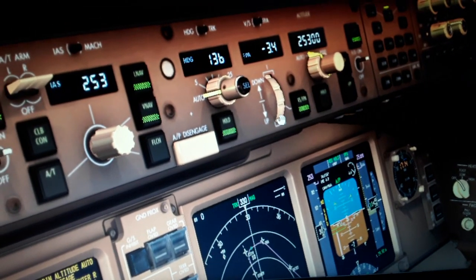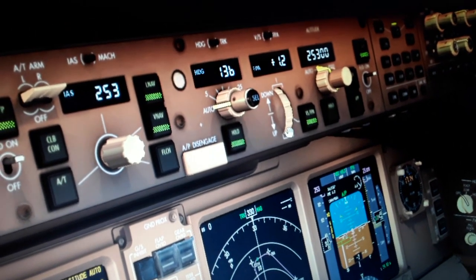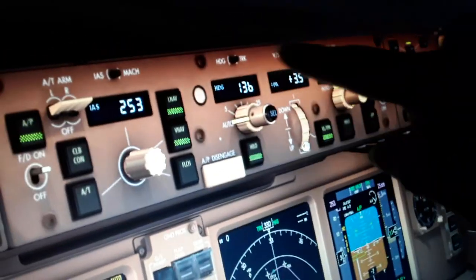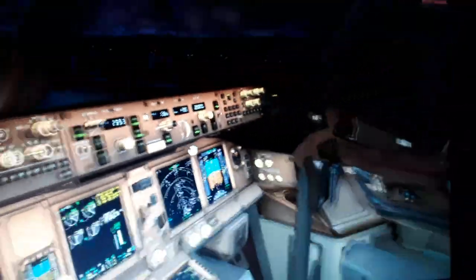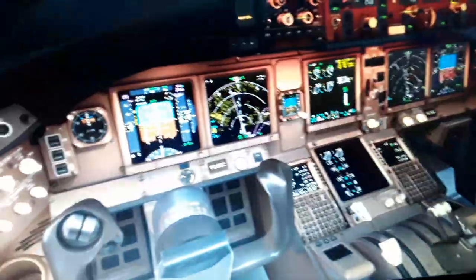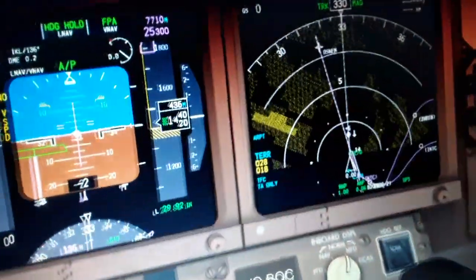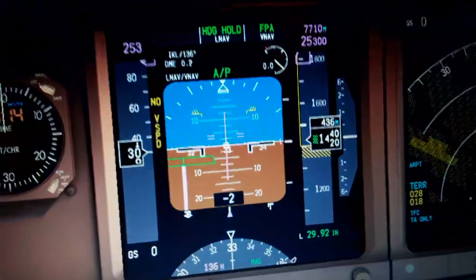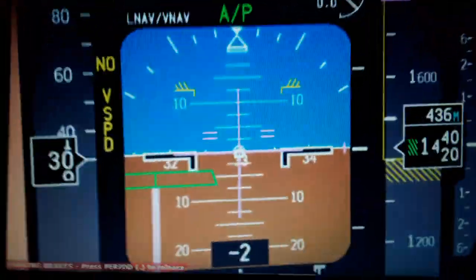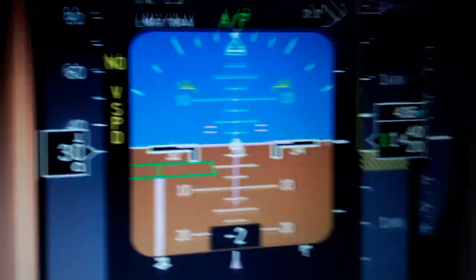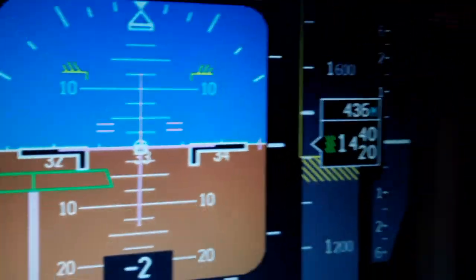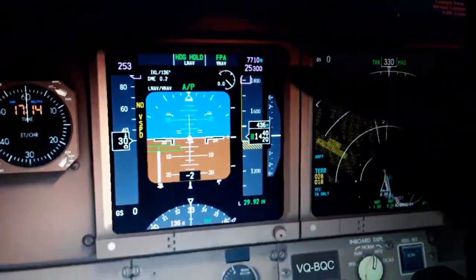Also I'm gonna show you the other way, plus 3.5 degrees. So this is gonna give us a climb rate now. So we have the aircraft coming in. Also we have another mode, a flight path angle, and the pitch altitude should be like that. As you can see, it's gonna be plus 3.5 degrees here between the 2.5 and the 5. So it will give us a climb to the target airspeed, target altitude.